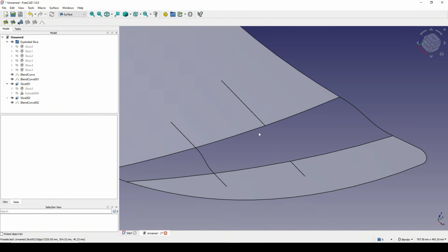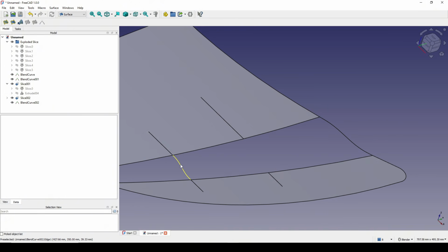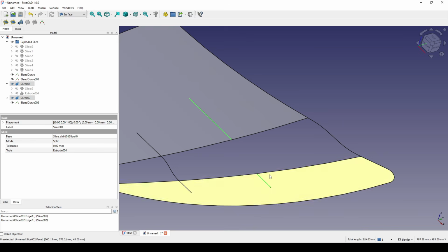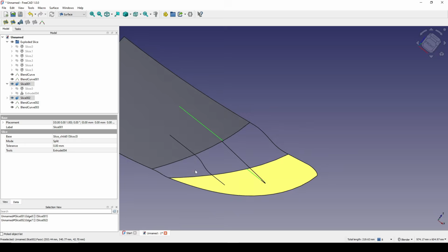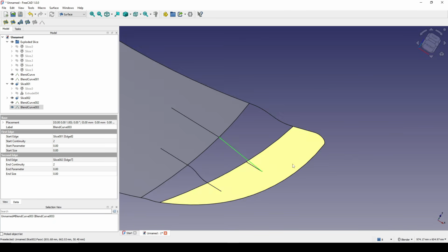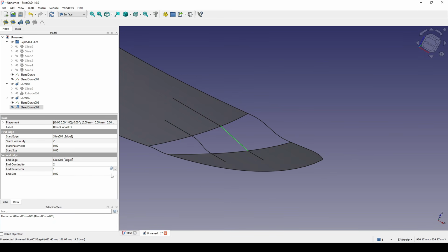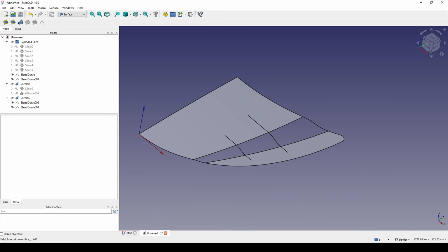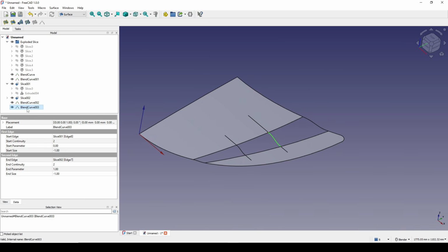So in here everything is zero. Plane curve is zero. Control select this edge and then this edge, and plane curve. Click on the plane curve and zero out the start size and the end size. Put 1 for the end parameter and then put the start size to 1. So 1, not good, so -1. The end size to 1, -1. Alright, now I have 4 plane curves.